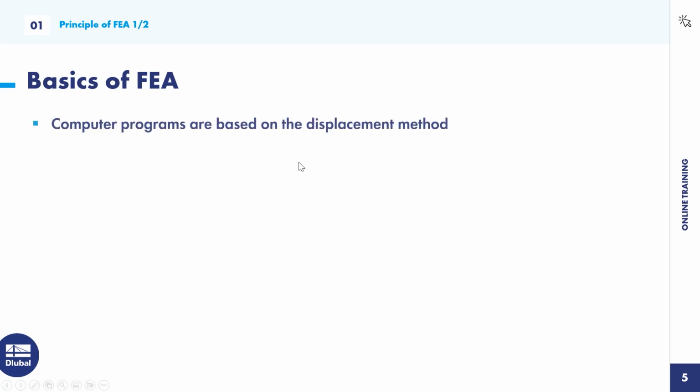The force method is called force method since the forces are the unknowns in this solving process. Within the displacement method, we have the displacements as the unknowns. The displacement method is, in this case, more important for us since it is implemented within RFEM. So also most computer programs will use the displacement method.